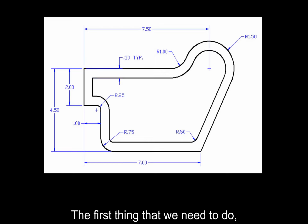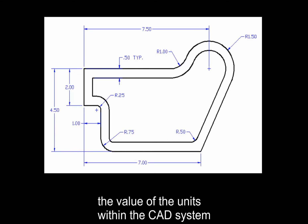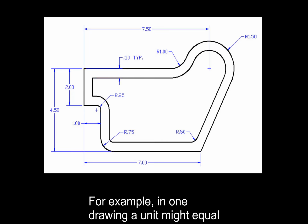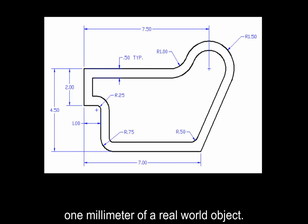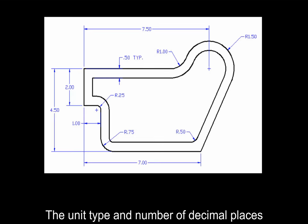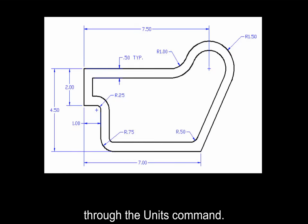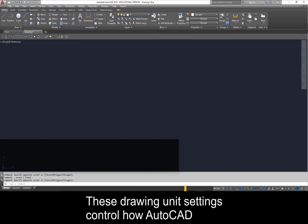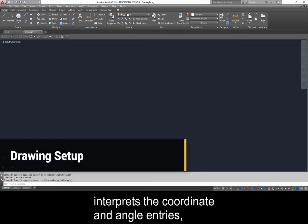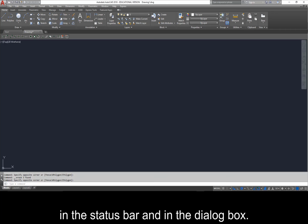The first thing that we need to do before creating the first geometric entity is to determine the value of the units within the CAD system. For example, in one drawing, a unit might equal 1 millimeter of a real-world object. In another drawing, a unit might equal an inch. The unit type and number of decimal places for object lengths and angles can be set through the units command. These drawing unit settings control how AutoCAD interprets the coordinate and angle entries and how it displays coordinates and units in the status bar and in the dialog box.